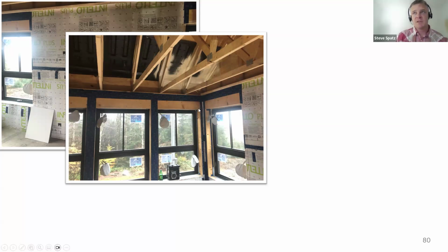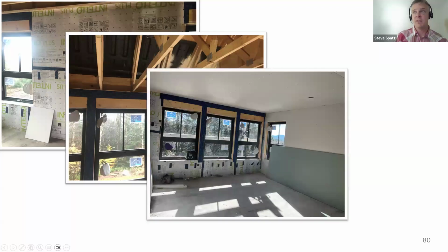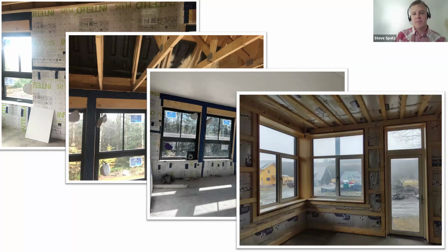Where you have transitions that are all framing, blocks of windows installed, where you just have stacks of supporting framing components, using a compatible airtight vapor open tape can be used in place of using the vapor control membrane, but making sure that you're integrating this all to make it airtight, and then your interior finishes going up over top of those components. You don't need to rely on the drywall being airtight at that point, because you've already detailed your vapor control layer with those details in mind.